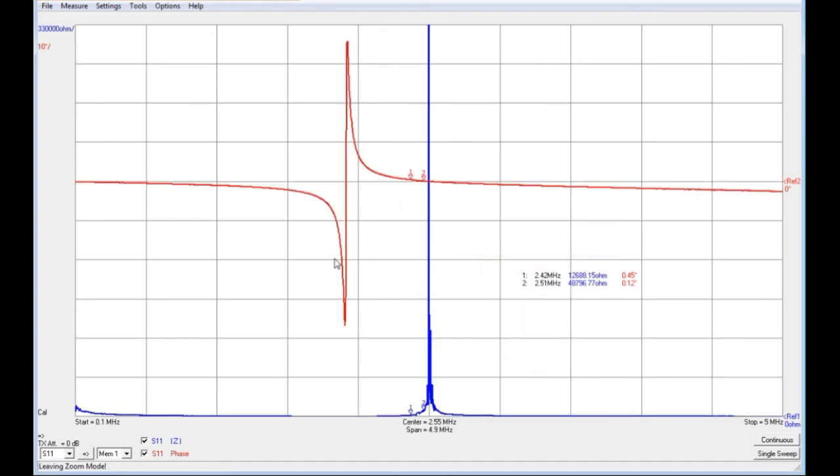I want to look at this region because this is a series fed measurement, so I'm looking for the series resonance circuit to get the truly accurate resonant frequency of the secondary coil here. This is a series fed thing. I've got a resonant coil sitting on top of the output of the VNA like it was an aerial. Now when we reach resonant frequency, obviously there's a series resonance circuit. The inductance and capacitance will balance each other, cancel each other out, in a way that we'll just be left with the internal resistance of the coils sitting on top of the vector network analyzer.